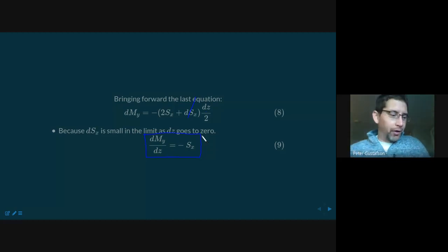Now, you guys may be wondering, why are we doing this? Why are we spending all this time calculating these not terribly difficult equilibrium statements? The reason is that we're ultimately deriving our beam equations, the governing differential equations of beam deflection. We had written moment equation terms before, but we didn't deal with how moments change as a function of position. So now we're expressing how moments change as a function of position. And by the way, in doing so, we now highlight that last load type that I referred to at the beginning of our beam lecture. That is the resultant loads, which are either the moments, the shear resultants, the axial resultants, or the torques. We're going to defer the torques till another lecture, but we've now done everything but torque.